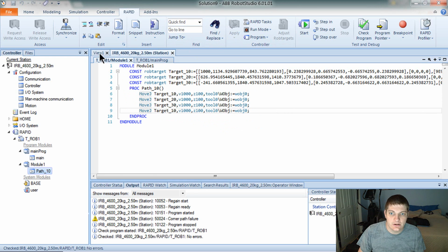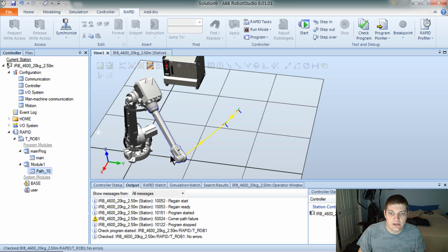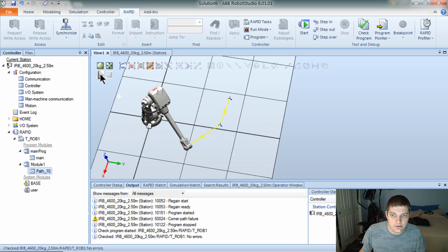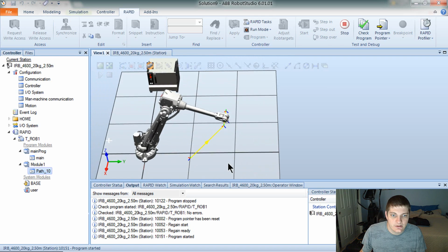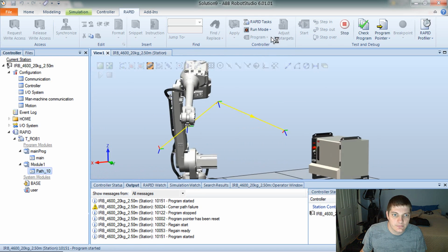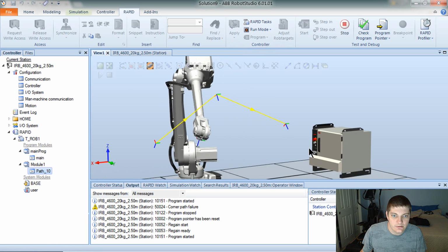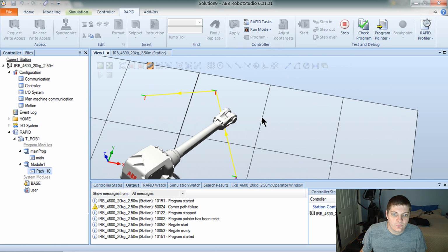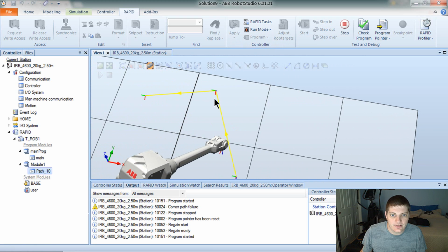And what it can do is actually, rather than creating a joint path for each of these joints and making the robot move gently across this line, or within a tight constraint of this line, it will actually just get the robot there. So let's play that now that we changed those to joints and see what he does. So you can see he's swinging way wide. Let's keep him going. Let's put him in continuous here. So you can see he's not following the path at all, really.